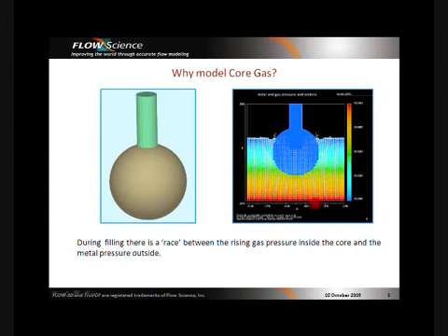As the core is heated, the gas pressure inside builds up. At the same time, the metal hydrostatic pressure outside the core increases as the cavity fills, which you can notice here. Typically, it is a race between the 2 processes. If the metal pressure builds up faster, there will be no gas blow into the metal, which is what we want.